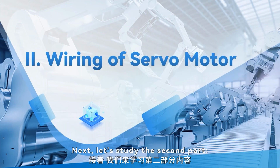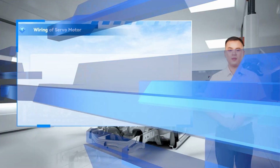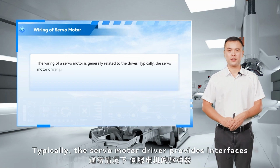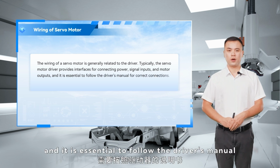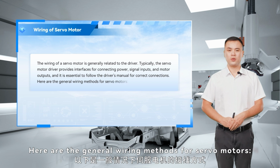Next, let's study the second part, the wiring principles of servo motor. The wiring of a servo motor is generally related to the driver. Typically, the servo motor driver provides interfaces for connecting power, signal inputs, and motor outputs, and it is essential to follow the driver's manual for correct connections. Here are the general wiring methods for servo motors.